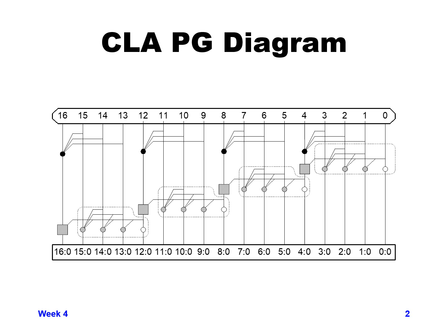You can see the longest path through this particular design is if we take bits 1 through 4 and do a combined carry look ahead function on that. At bit 4 you can see the black circle for that combined carry look ahead function. Then we have our normal carry skip at bit 4, which is the gray square.